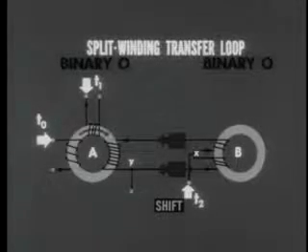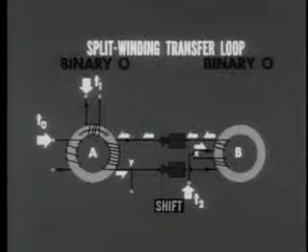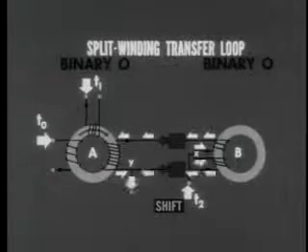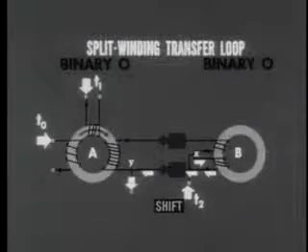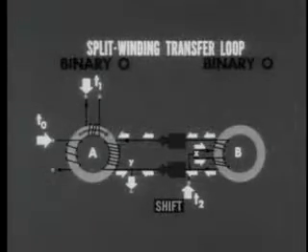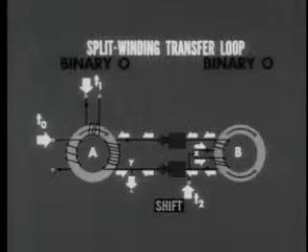The result is no change in either core. Core A remains at 0 because the upper branch current is applied to its winding as a dot pulse. The upper and lower branch currents are equal, and therefore core B also remains at 0 because equal currents there produce opposing but equal magnetic fluxes, which cancel out.